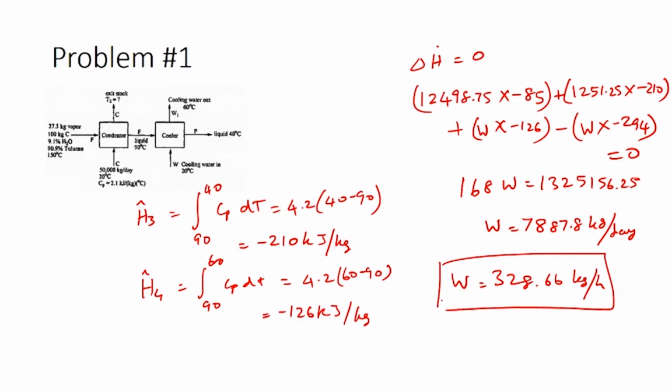With this we have actually looked at a simple example problem where we had a multi-unit process where both the processes had energy balances that can be performed, and we had a system where there was no reaction as such, there was only phase change which was happening, and we were looking to perform the energy balances required to calculate the temperature of an exit stream and also the mass which is required for an inlet stream to get the desired levels of cooling. So, with this we have performed one example problem for the energy balance review.